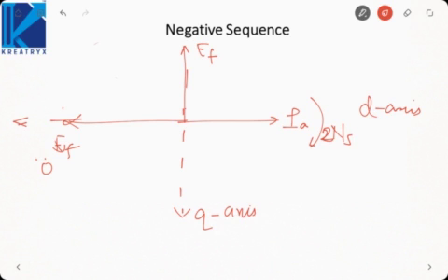So it will alternately lie along the d-axis and q-axis because it is rotating with respect to the field MMF, or with respect to the rotor axis. Sometimes it will lie along the rotor axis and at other times perpendicular to the rotor axis. So it will encounter the d-axis reactance as well as the q-axis reactance alternately. For half the time period it will have d-axis reactance, for half the time period q-axis reactance. That means the reactance it encounters depends on time. At some time it is xd, at other time it is xq.